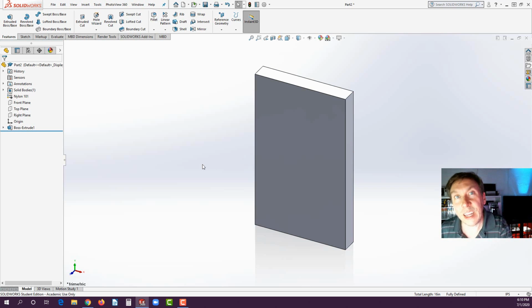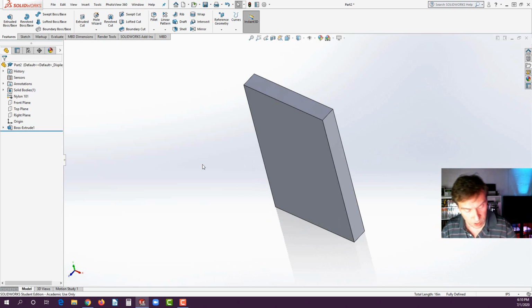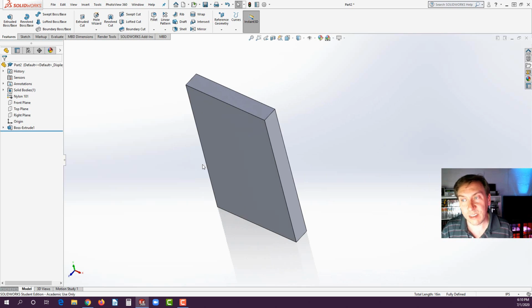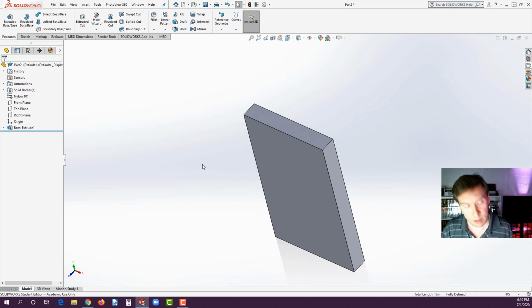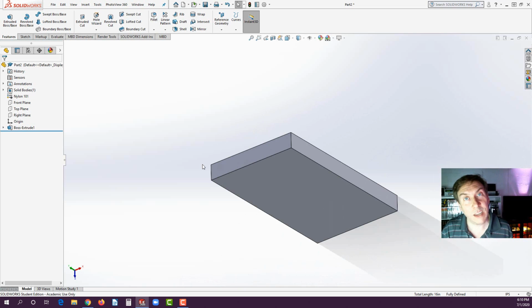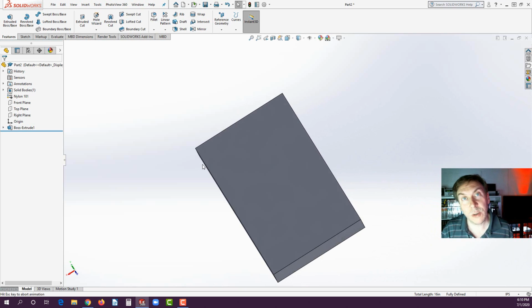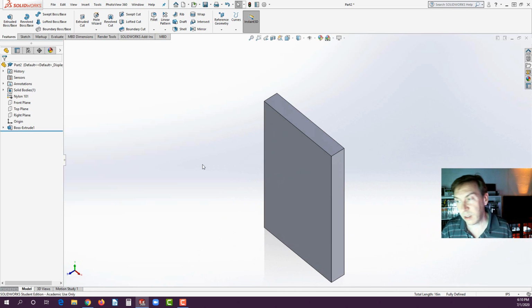Now we're going to take a look at how to rotate, orient, and pan, all those fun things. First of all, before you do anything, hit the arrow keys on your keyboard, left and right, up and down. You'll see it rotates in 15-degree increments using the arrow keys. Hold Control and hit your arrow keys, and that's pan. Hold Alt and your arrow keys, and that's clockwise or counterclockwise rotation. Shift and your arrow keys rotates in 90-degree increments.